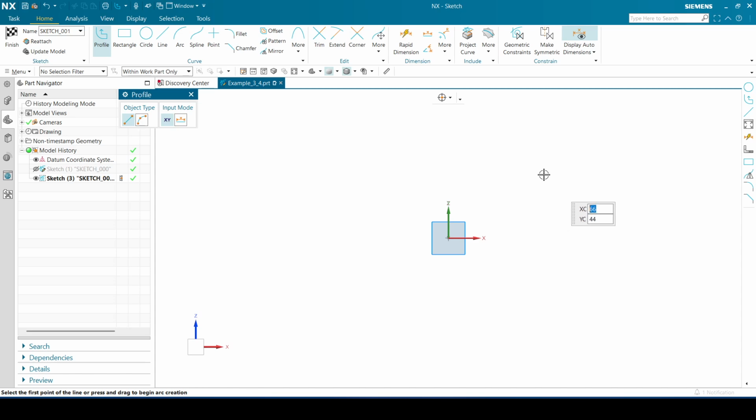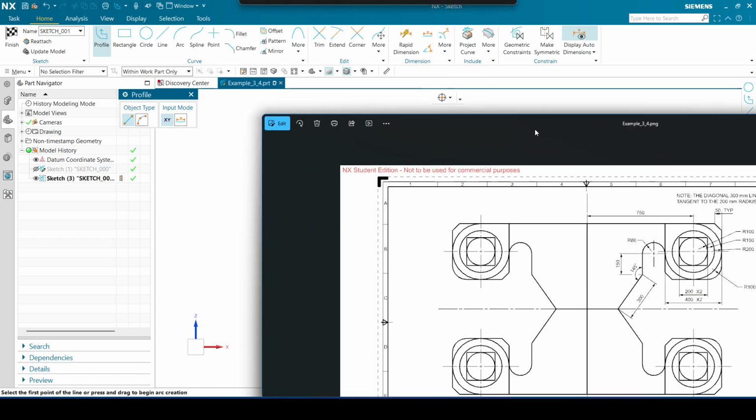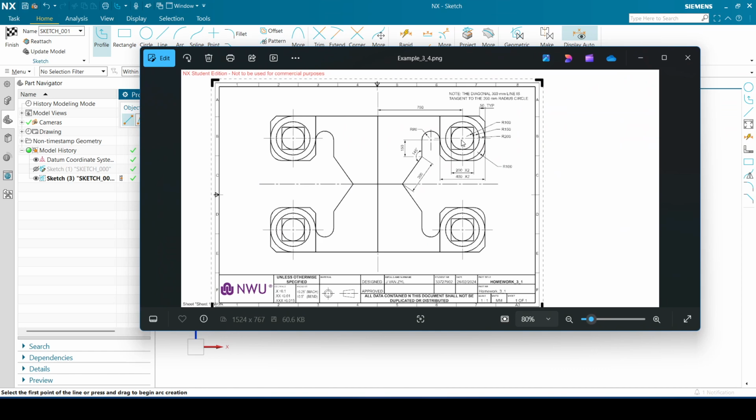So, okay, thinking forward, because last year we did not tell the students where to place their datum system, or at least in the first sketches. For this year's homework, we will be telling you that. But last year, people put it everywhere, and most of them started on the origin, which is usually a good principle. However, looking forward for this one, it's not that good of an idea. So let me quickly just bring that sketch back to show you, because you can see here, in the end, we're going to mirror and then mirror again.